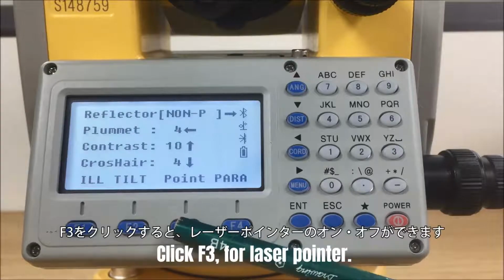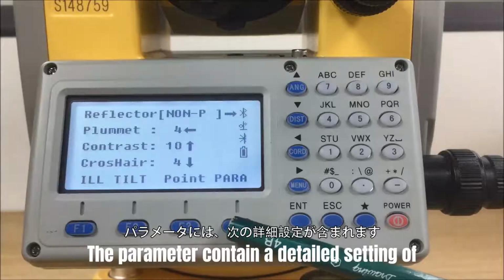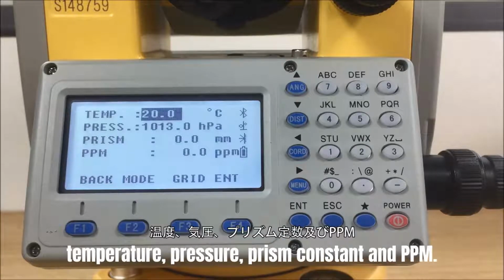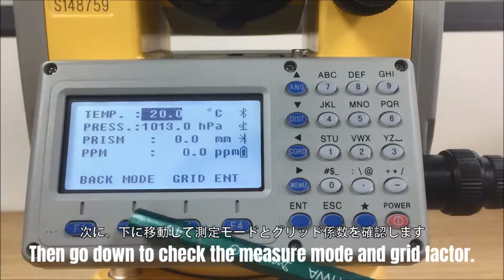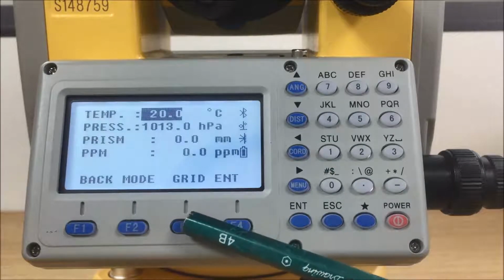F3 is for the laser pointer. Click it once to activate the laser point. The parameter contains a detailed setting of temperature, pressure, prism constant and ppm. Then go down to check the measure mode and grid factor, and adapt the total station to your own requirements.